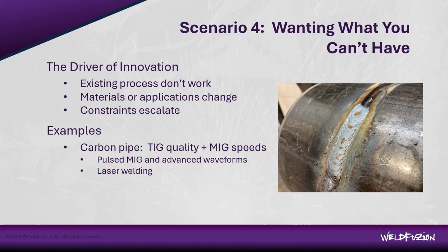Now, the welder can make the root, the fill, and the cap without changing the processes, simplifying the setup, simplifying the equipment, and MIG welding is 4 to 5 times faster than TIG welding. So it drastically improves economics and lowers the number one cost in welding, labor. MIG welding is also much easier to automate, so it opens the door for even more productivity gains.